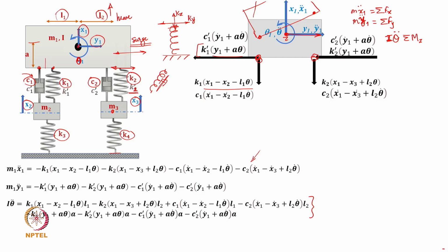Now, having obtained these forces acting on the free body, you can generate the governing equation by applying Newton's law. If you look at all the vertical forces or vertical motion, mass times acceleration will be the summation of all the forces in the direction of acceleration in the vertical direction. If you use this, you will get this expression, which is going to be the governing equation of motion for the degree of freedom x1.